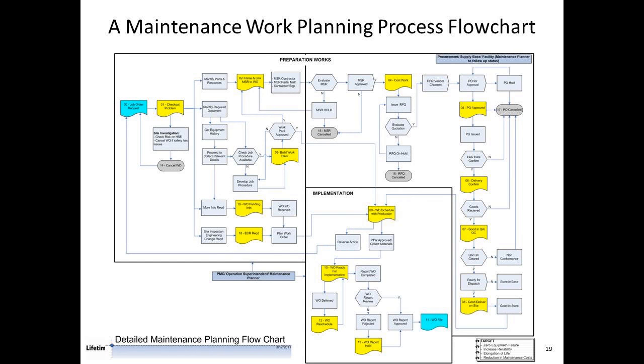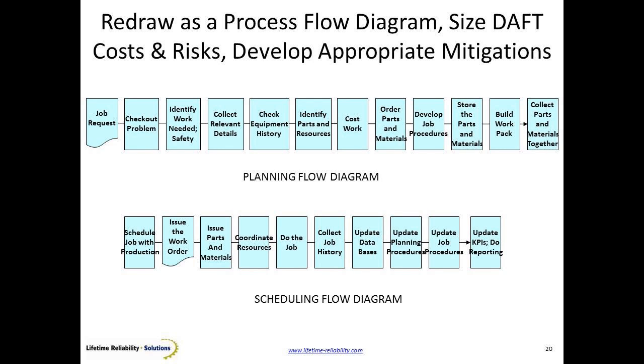This particular slide here is a planning process for maintenance work, and a lot of companies will have flow diagrams like this. They are not much use to us in this fashion. What we have to do is interpret those flow diagrams into reliability block diagrams, convert that previous flow chart into a series arrangement.